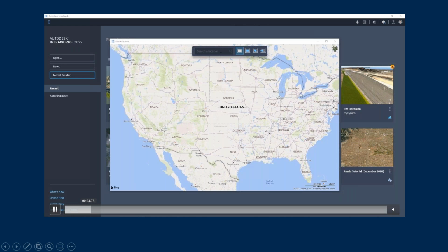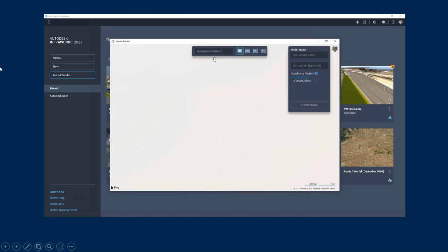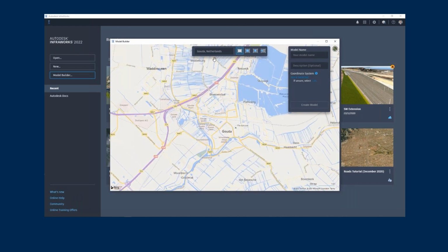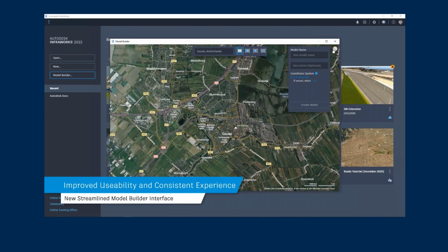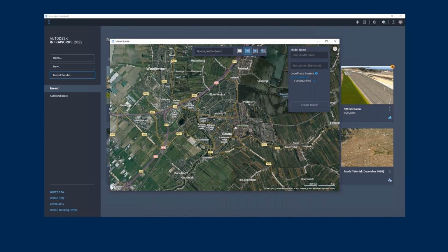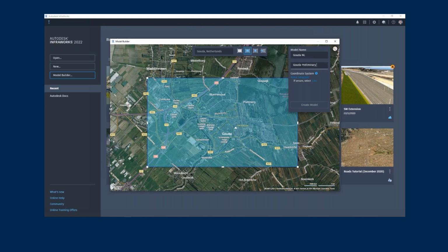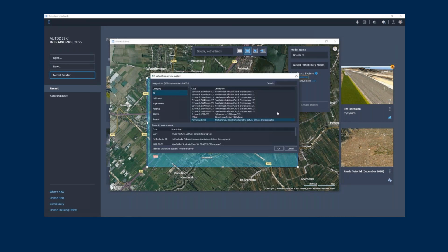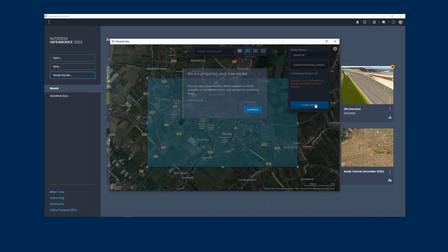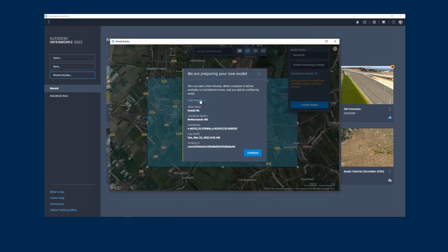So as you can see here, this is the model builder that we're talking about, where you would normally just enter the address of your site, create the site extent as a polygon or view, and of course give it a name. You should have seen this in my many webinars before, as well as you would need to assign a coordinate system. So here in South Africa, our coordinate systems are there, so it's quite cool, and we can geolocate our model accordingly.